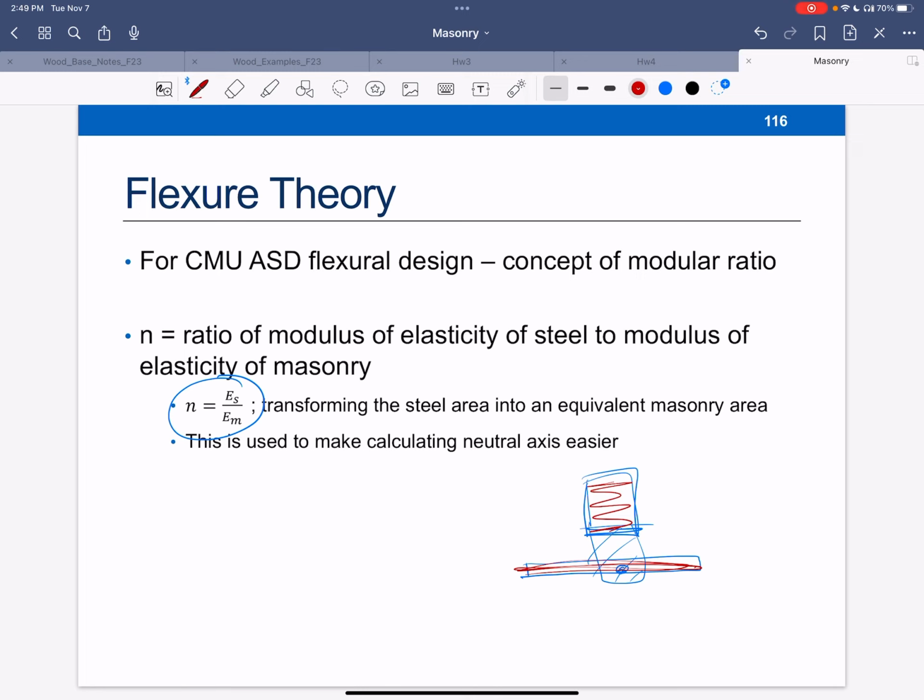So this is easier to find the neutral axis when we're doing this. In concrete, we're calculating an A term and some other different things. Here, I actually want to know where the neutral axis is, okay, which we could find in concrete too, because A was related to little c, which was the distance to the neutral axis. So bear with me, we'll do that. But you did a lot of this when you were in your mechanics class, hopefully. And you probably even did examples with concrete. You may have done some of it in reinforced concrete if you were looking at deflections.